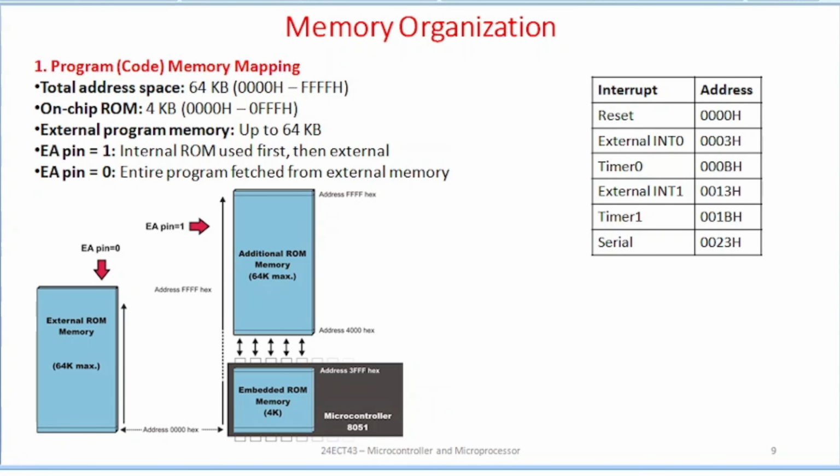Here it is also used for the programming code with the help of the interrupts: reset at 0000H, external interrupt 0 at 0003H, timer 0 at 000BH, external interrupt 1 at 0013H, timer 1 at 001BH, and serial port communication at 0023H.